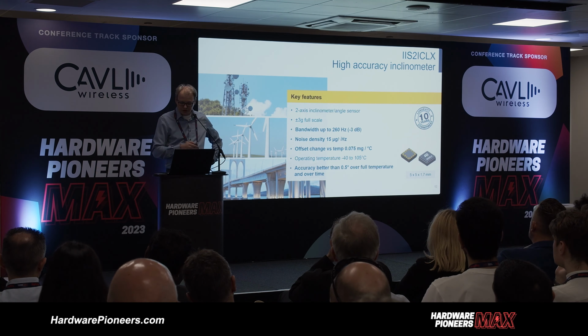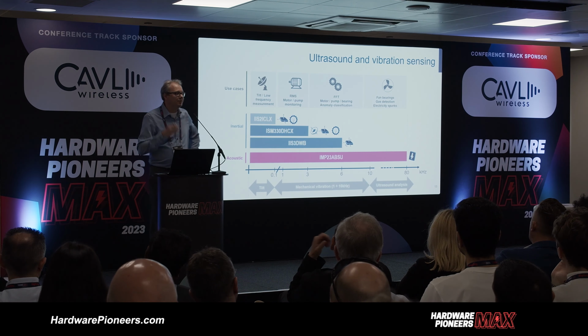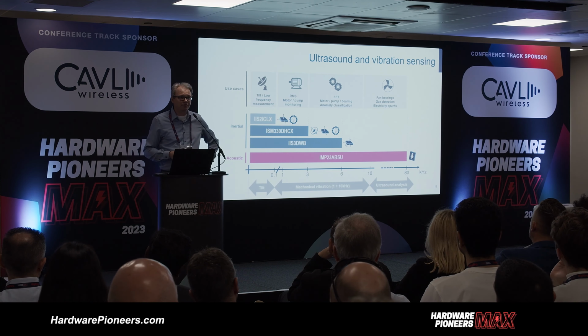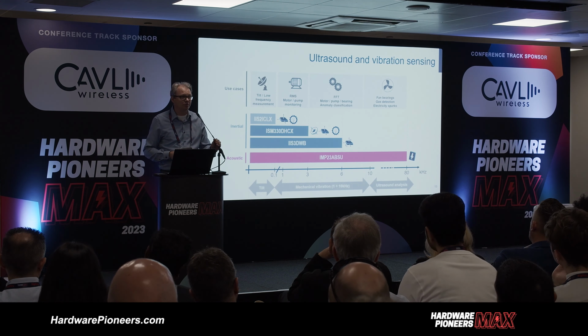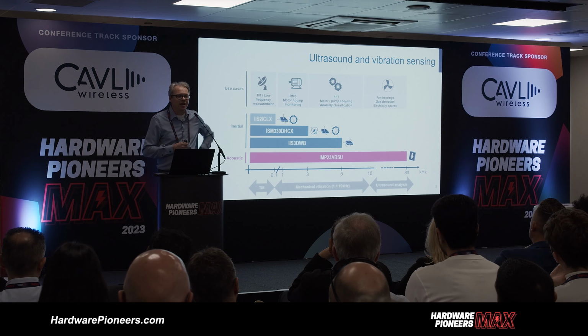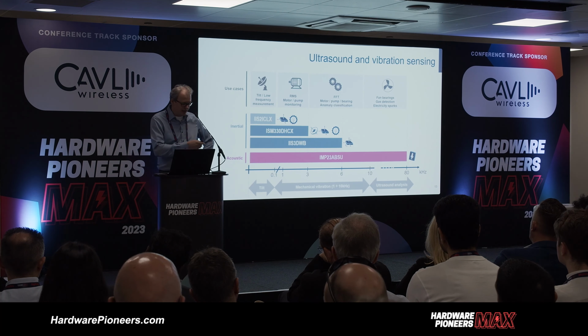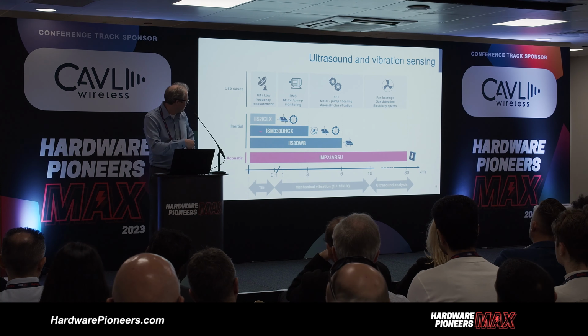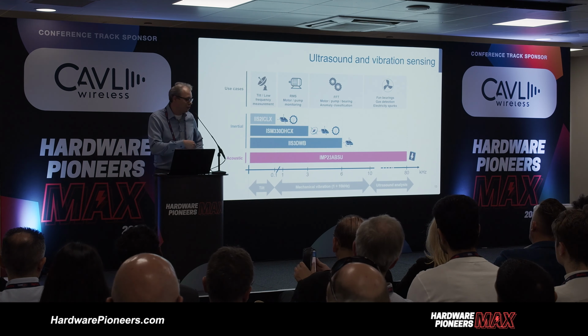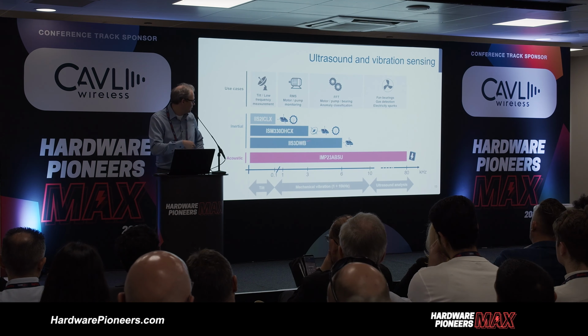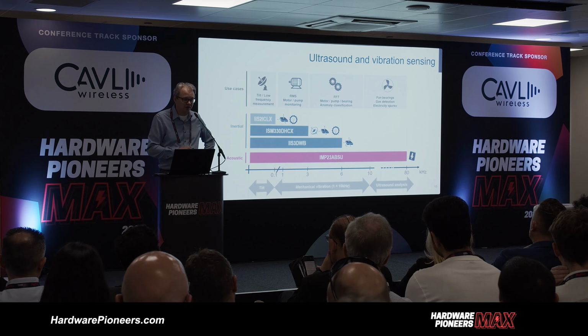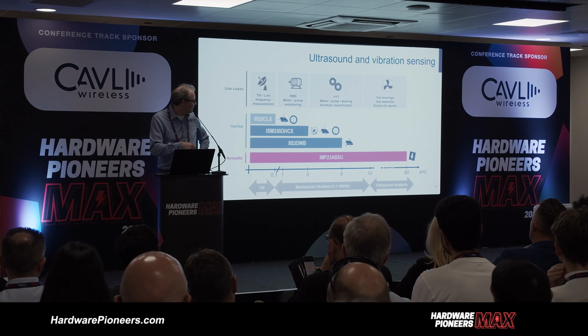But in short, to summarize, the message is that we have plenty of different kinds of sensors, and they are all optimized for different purposes. To benefit from AI, you need to have the right kind of sensor to measure the right things. As I mentioned, this inclinometer was for very small frequencies. This 6-axis component went up to 2-3 kilohertz, and this one went up to 6 kilohertz for motors and pumps. And with the microphones, you could go up to 80 kilohertz.